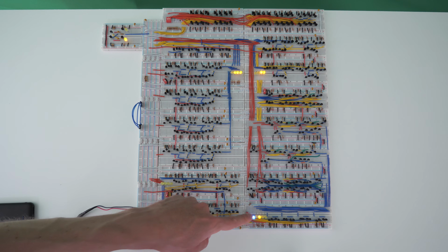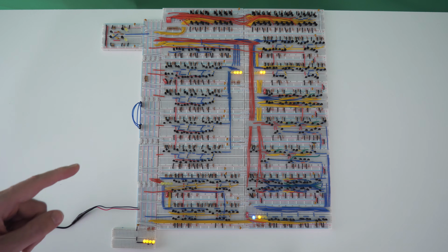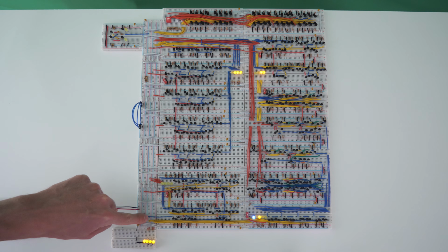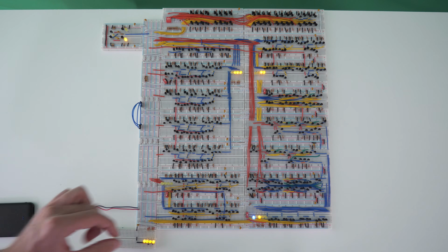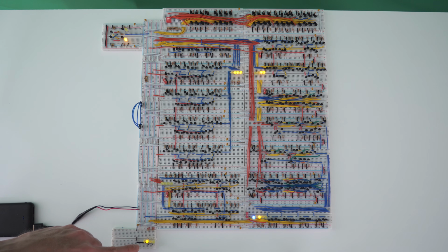You can see that we actually have this blue light also enabled, which is our carry bit, but that's actually what we expect whenever we're doing a subtract command. It's perfectly fine. The only thing that's going to be sent to our data bus is the value of 4. So whenever we enable this here, now we have a value of 4 being sent to the data bus. And this was actually the last command that we needed to run in our program.